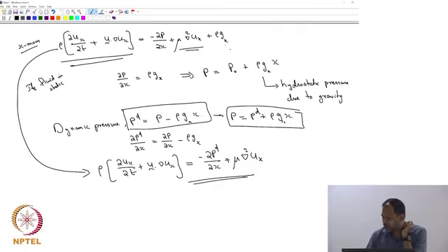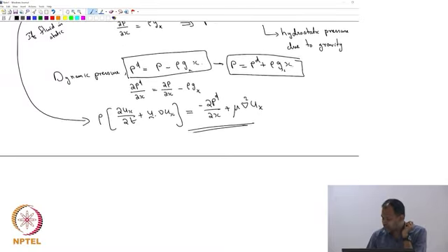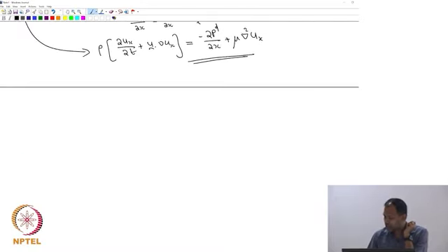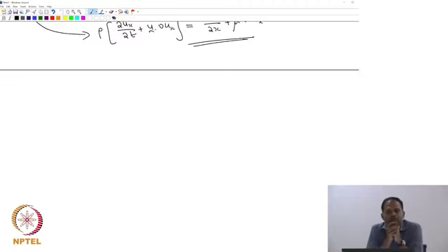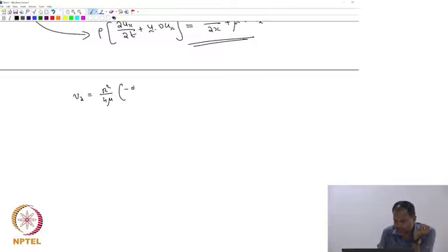So what would it look like if you write down, let's say, the velocity profile for our pipe flow? Can you write down V_z explicitly? So we got V_z is equal to what? Some R squared divided by 4 mu, into minus dP/dz, into 1 minus (r by R) whole squared. That was the expression. What pressure is this?